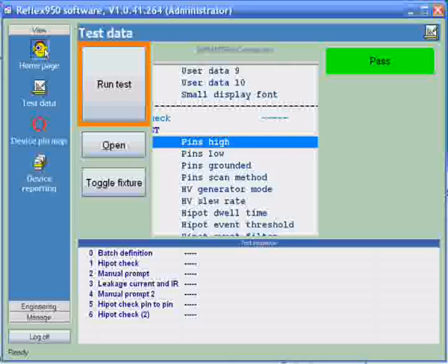The pin editor for this is shown here, and you can see that the layout of the sequence has only resulted in some 8 steps, and if we click through these you can see what they will be. And this enables you to verify that in fact the application of the test voltage is as you expect.